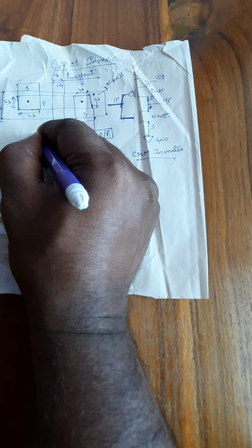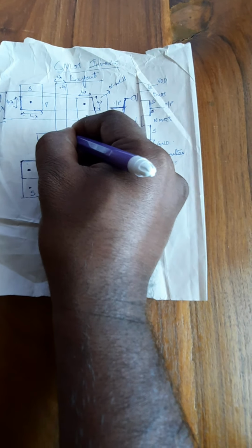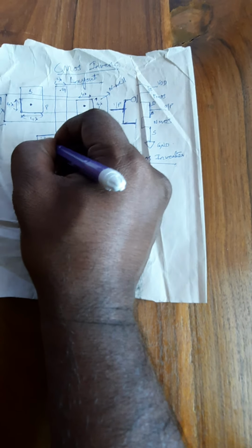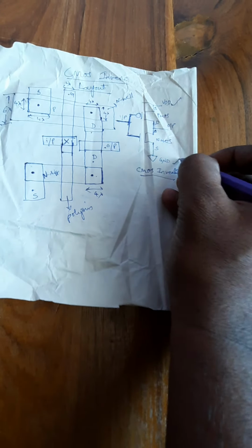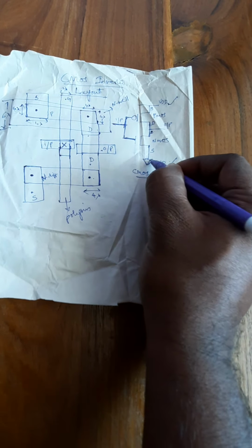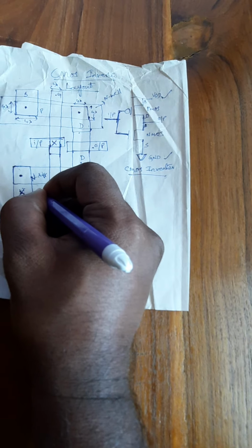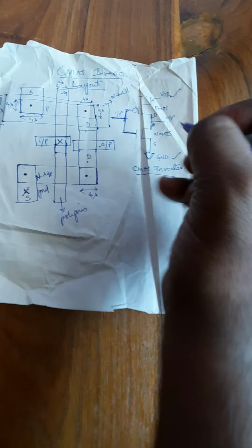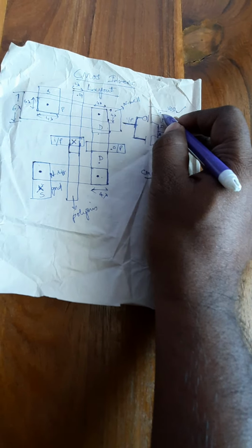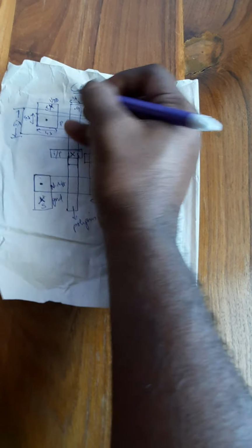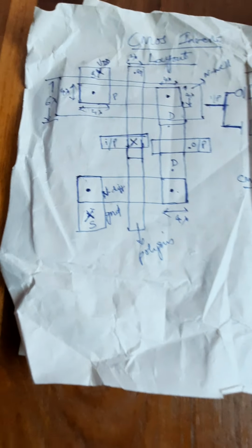Since I have used a metal layer upon the polysilicon, I'll be using one kind of contact over here wherever this crossing of metal takes place upon the poly. So now this will act as my input terminal. Now we have completed the layout of a PMOS and NMOS. The next important point is you are supposed to give the VDD and ground terminal. The ground is connected to the source of NMOS, so here you make a ground terminal with the help of a cross mark, and this will act as GND, and here the VDD should be connected to the source of PMOS. So here the VDD is connected with the help of this contact, that is VDD, and this is a complete layout of your CMOS inverter.